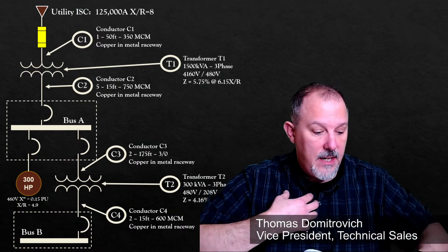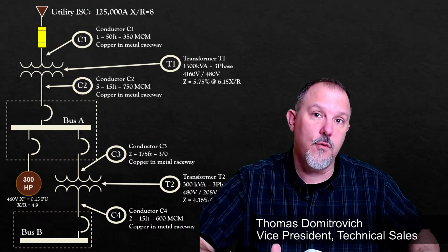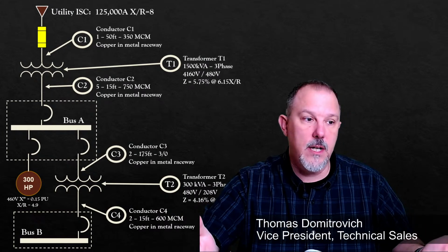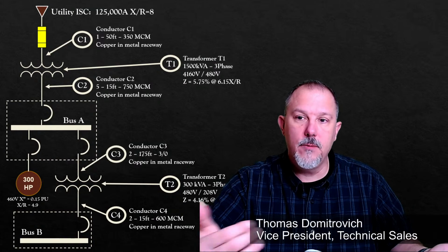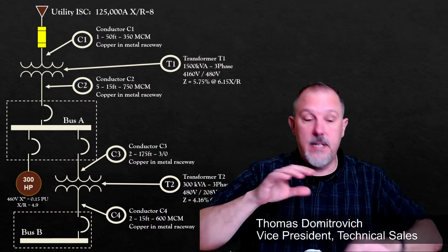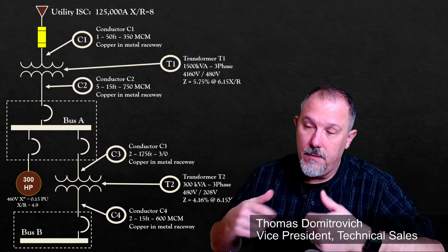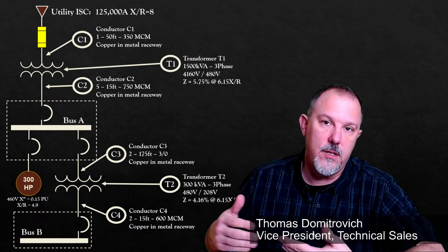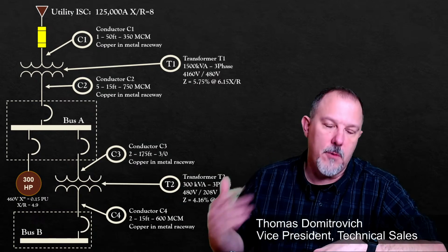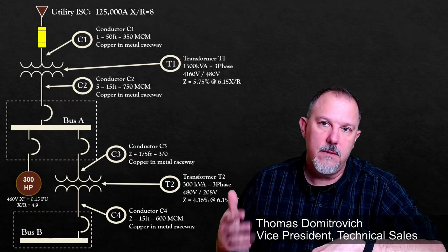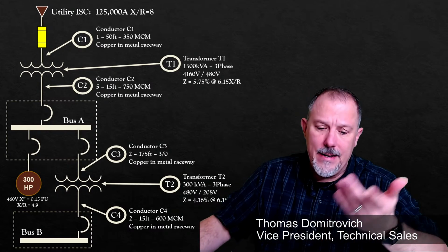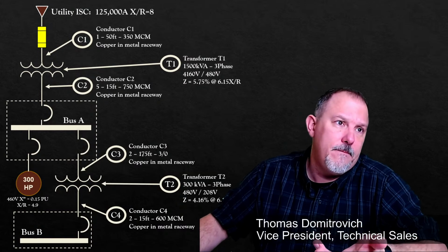My guess is that if you're trying to energize a transformer and you keep tripping the breaker, and it may be on the third time it holds in, you're cutting it really close on the instantaneous. Those are the types of considerations from a reliability perspective. You don't want to have to keep closing in a circuit breaker just to get it to hold because of that inrush current.